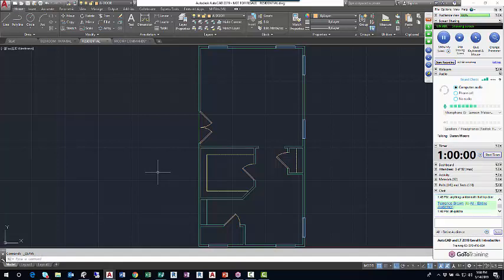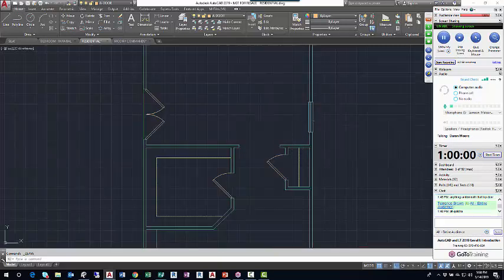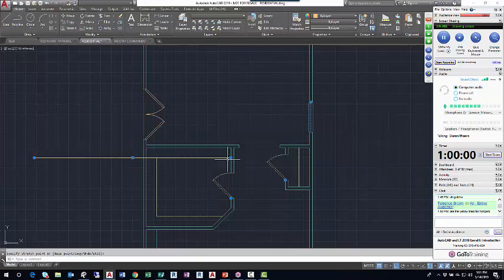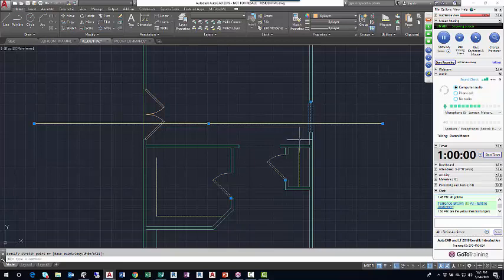Questions at all? I don't know if I've shown you this. Maybe you've already seen it. If I click on a block, the whole thing highlights as a unit. All these blocks will. If I click on a line, one line highlights as a unit. I've got 3 grips on a line. The endpoint grips allow me to stretch the line. The midpoint grip allows me to move the line. These are pretty simple edits. I wouldn't do a lot of these.